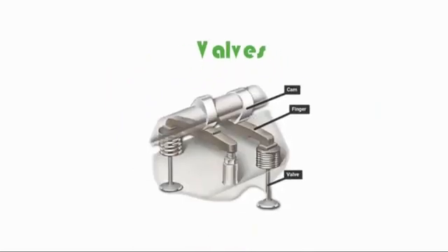Valves. The intake and exhaust valves open at the proper time to let in air and fuel, and to let out exhaust. Note that both valves are closed during compression and combustion, so that the combustion chamber is sealed.